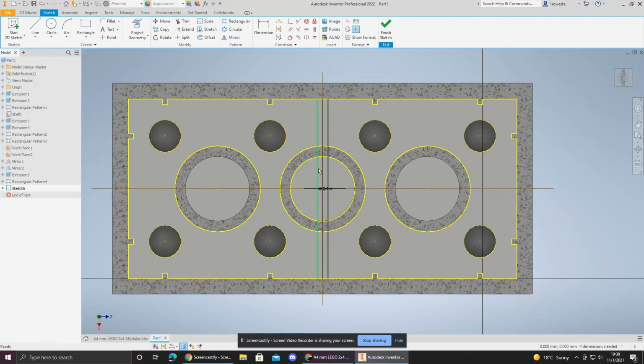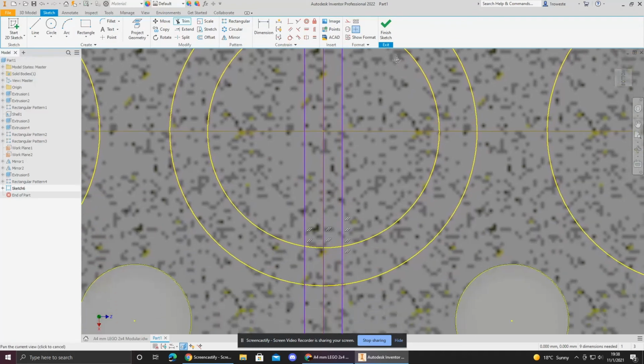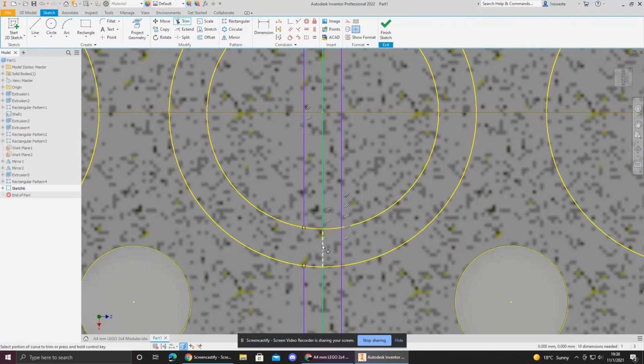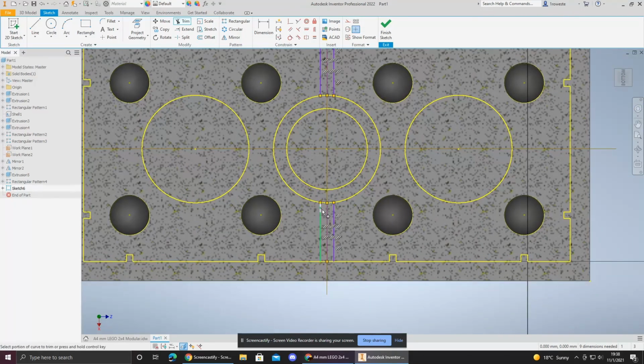If you would like to keep things clean, we may now use the trim tool in order to trim off the overlapping lines that bleed into the circle. This will perfectly cut them along that line of the circle, creating a perfectly clean extrusion for later.